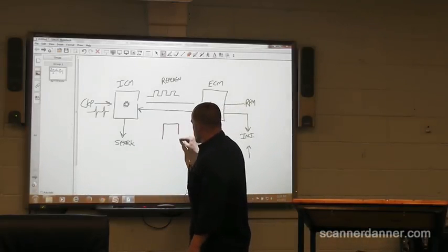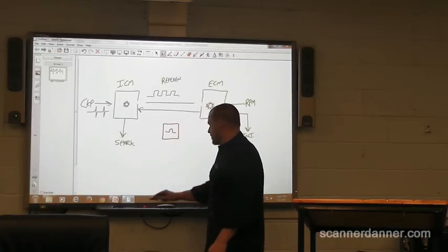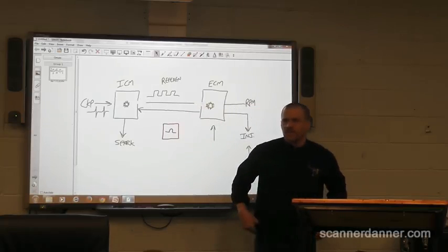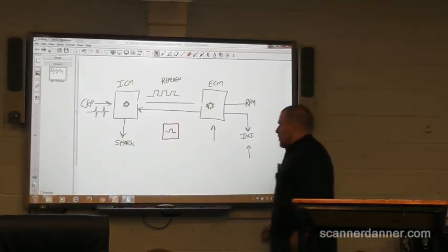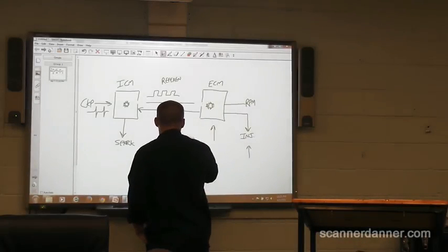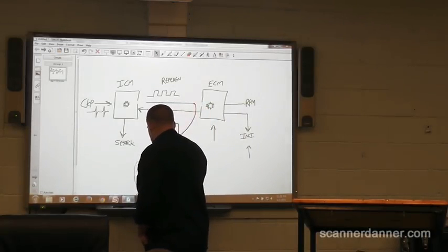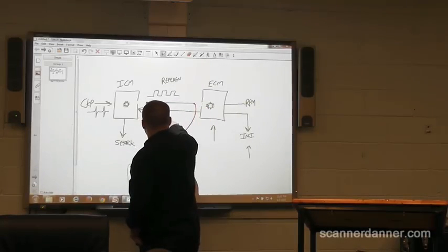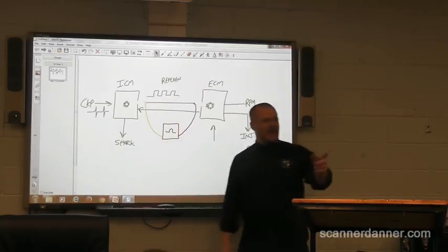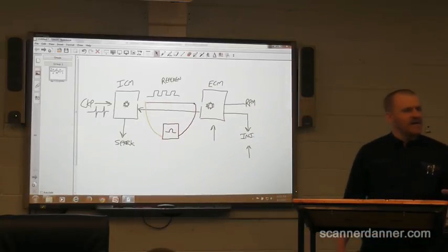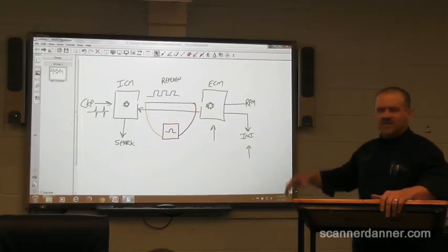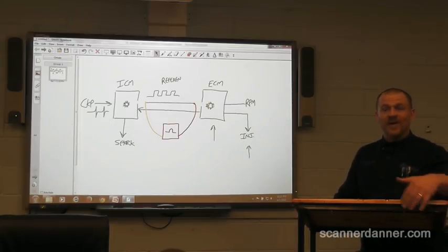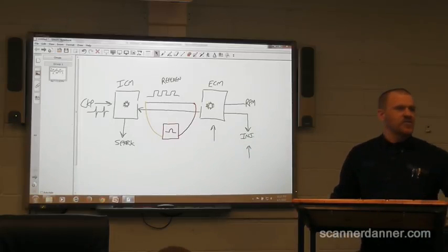Ohm meter, where do the leads go? First step. Each end of the wire. Each end of the wire would be incorrect, and that would be what everyone typically says, so that's okay that you, is it Matt? It's okay that you said that. That is an open circuit test. And remember, going into this, we were never concerned about an open circuit. We were concerned about a short to ground. So let's follow this through.